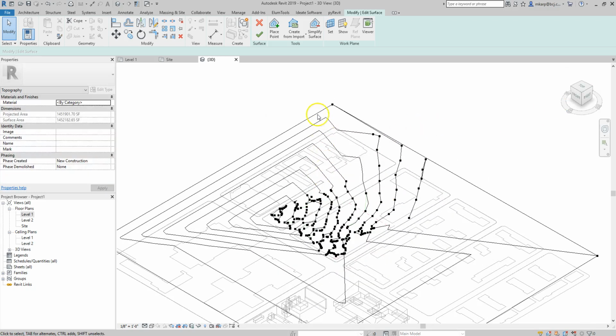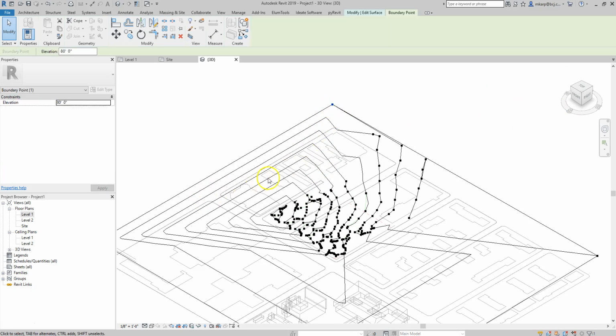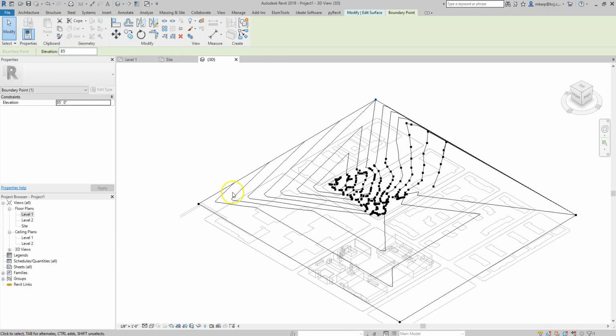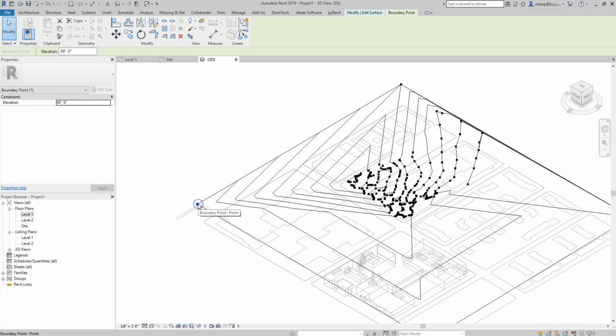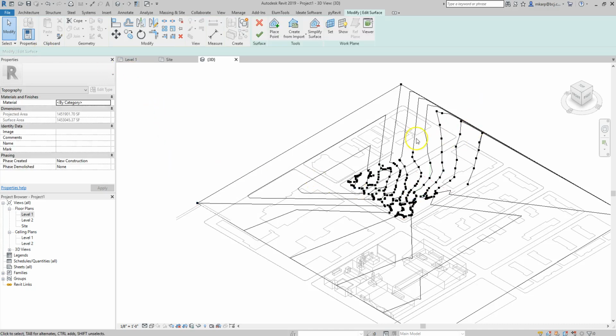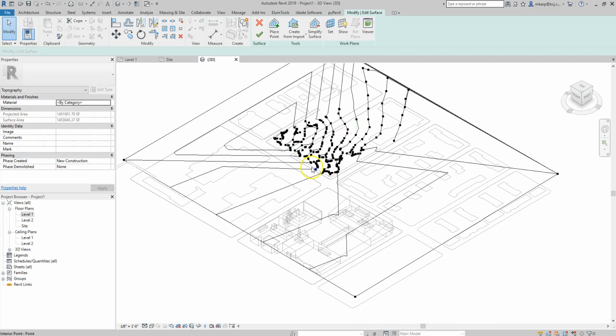We're still sloping a lot down over here. What you can do, if you don't want to slope down as much, is guesstimate how high this point would be. So when I click on that point, I could say, well, what if this was at 85? All right, so that looks a little bit better because we're not sloping all over the place. We can do the same thing over here. Get this up to 85. So you can clearly edit these points more as you learn more about where they probably actually are.